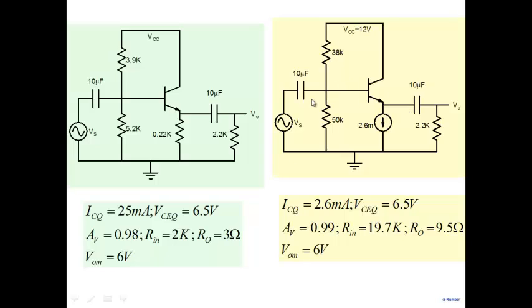So if we focus on input resistance here, input resistance is looking from here. As you look right at this particular point, what you see is these resistors will come in here, which is RB, and then whatever is the resistance looking into the base here. Now, if you look into the base here, what do you see now? Remember, if you look into the base, the net resistance is R pi plus 1 plus beta times RE, right? Now, if you look into the base, what is RE?